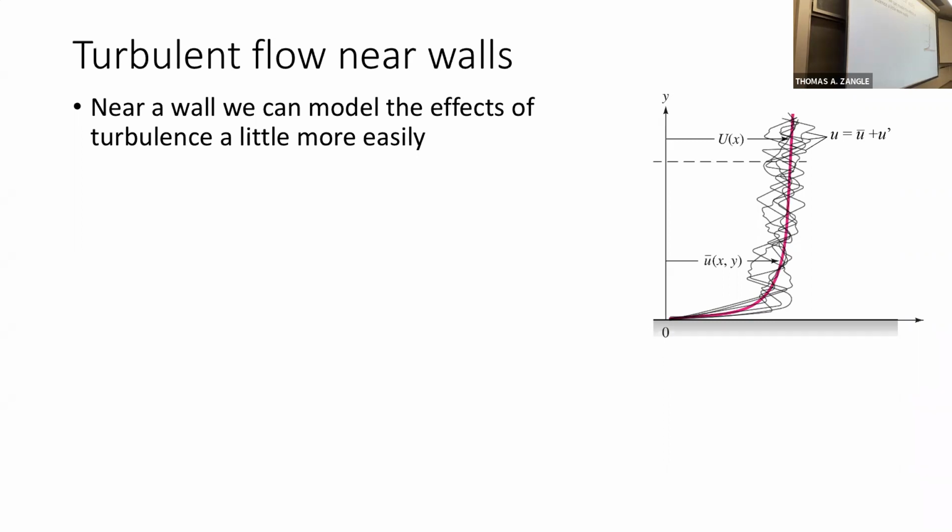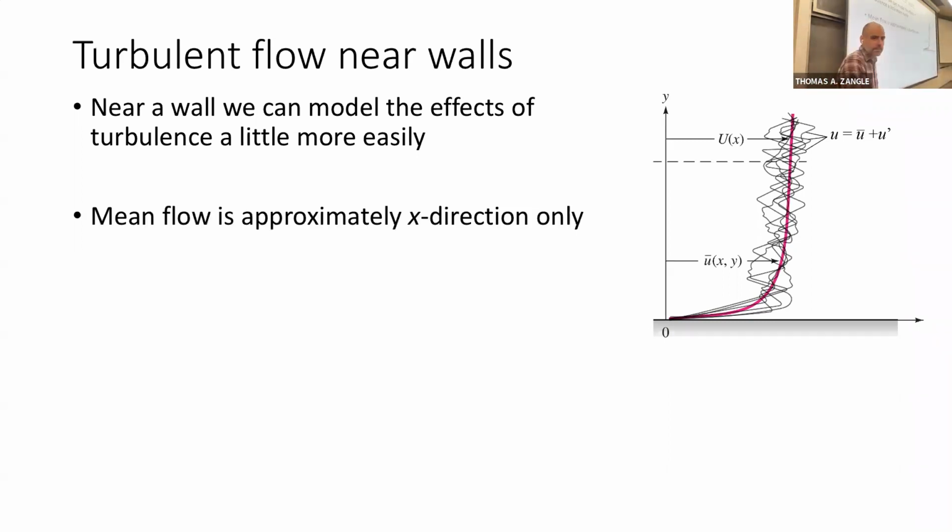At every point, over time, there are multiple possible answers. This is in stark contrast to the laminar flow case where there was one velocity profile. One of the things that makes turbulence challenging is that the instantaneous velocity profile varies and fluctuates. All of them are solutions to Navier-Stokes, so all of them are potentially valid solutions. But what we care about is the average velocity profile, the time average, and we'll see that we can actually get at least an approximation for that.